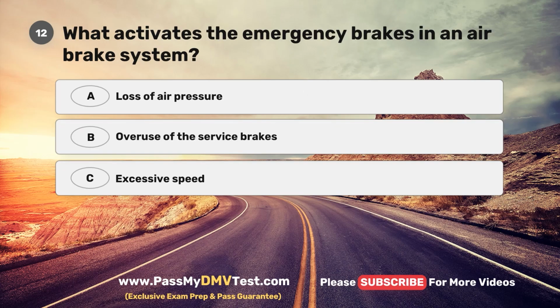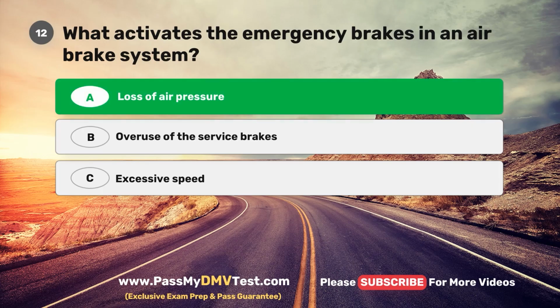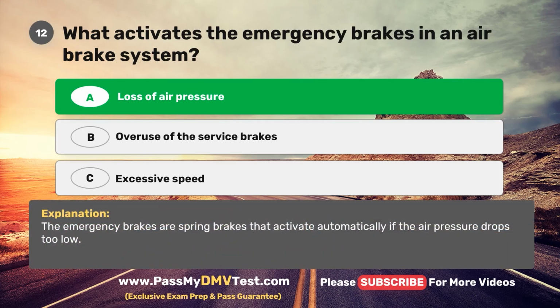Question 12. What activates the emergency brakes in an air brake system? A. Loss of air pressure. B. Overuse of the service brakes. C. Excessive speed. The correct answer is A. Loss of air pressure. The emergency brakes are spring brakes that activate automatically if the air pressure drops too low.